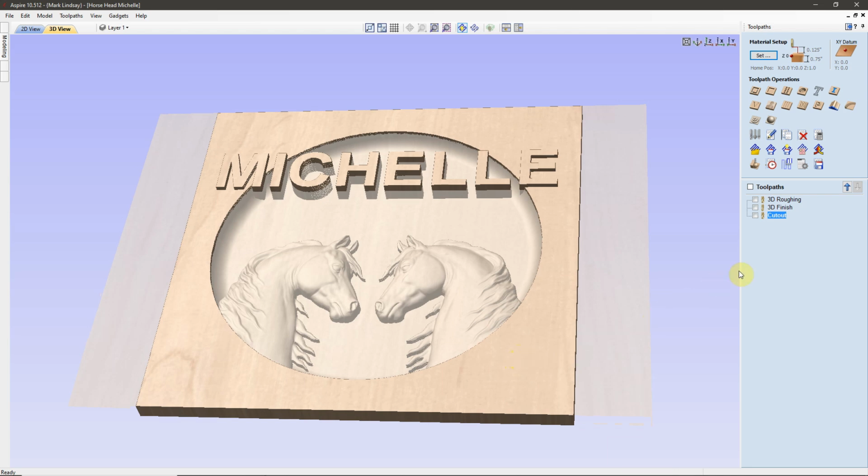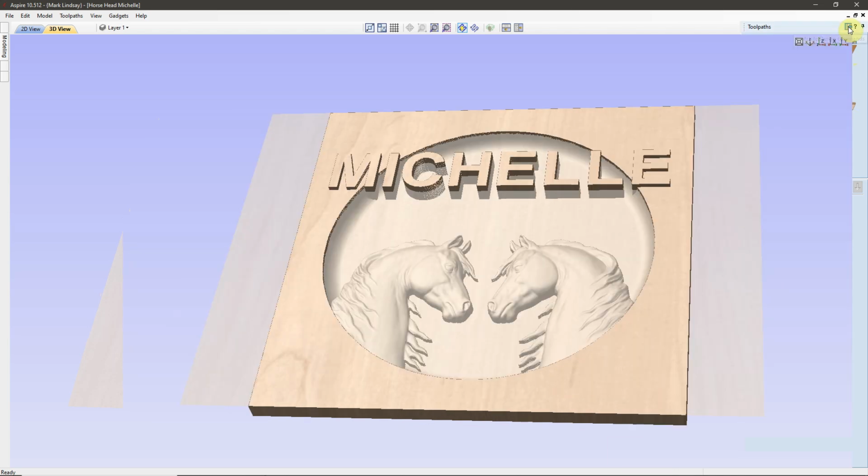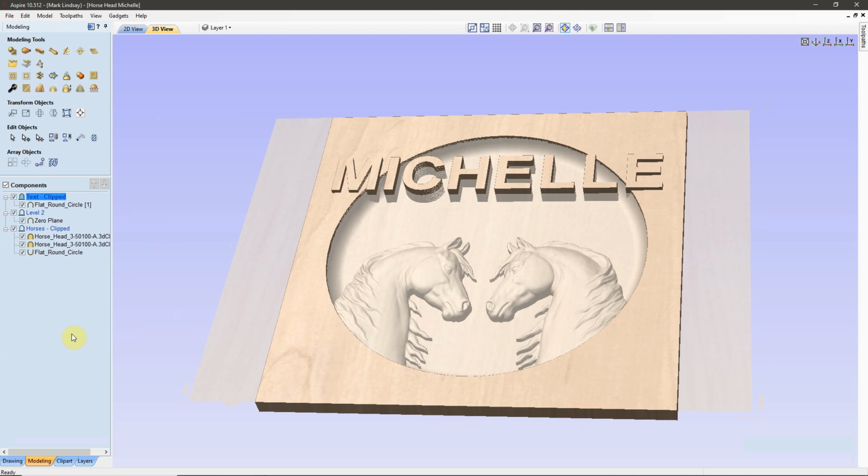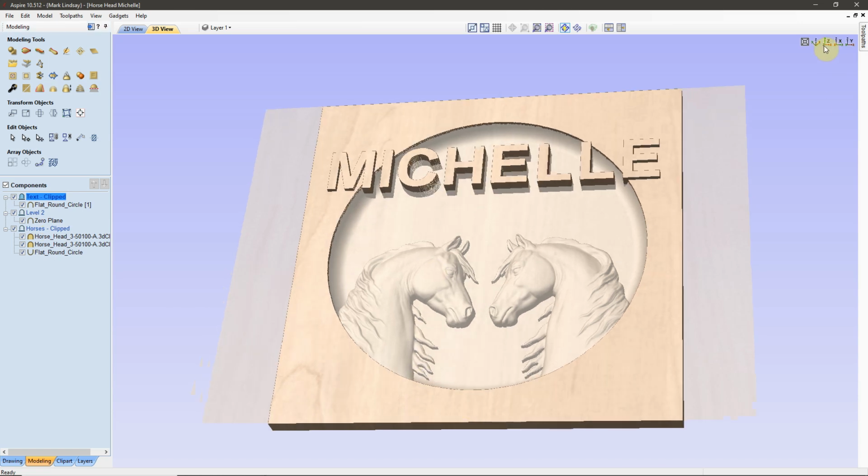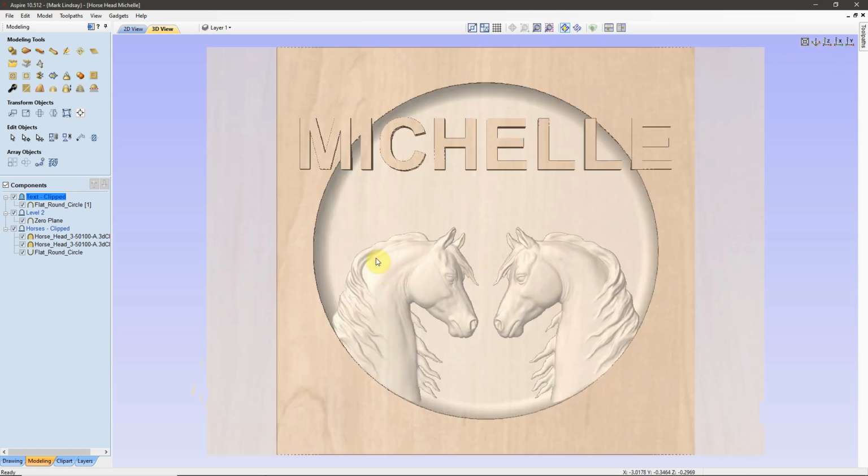While it may look complex, the thing to remember is keep your levels separated, and if you add more components and you add more processes, put them on their own level. It's easier to control the combine mode and the level clipping when you have them placed on separate levels.